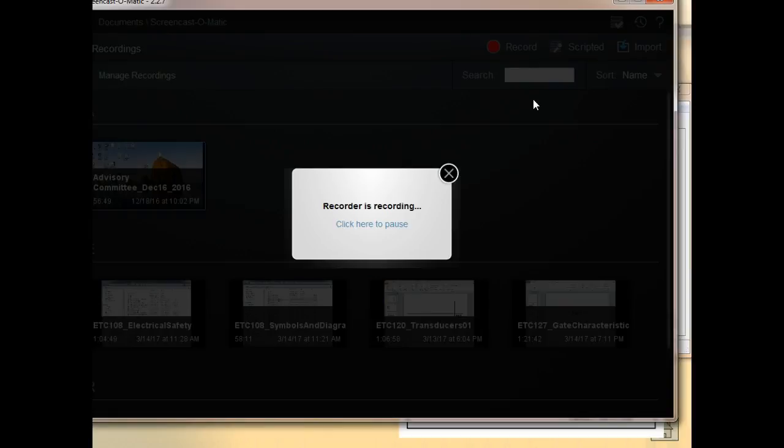Why? Because all the jumping is done what? Out in the circuit. The parallel is done out on the plugs. The plugs are designed, if you ever wired houses, one plug is designed to do what? To feed the next. They are designed to do that because that's where all our jumping goes. So we'll never see that. If you can't figure out how to do it, then that's something you need to work on. And if you was an electrician with a business, you'd go out of business real fast if you had to run every plug back to the panel box, right? You understand that? You'd be using about 50 times more wire than what's required to wire the house.